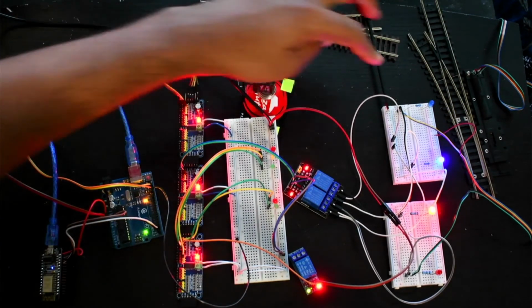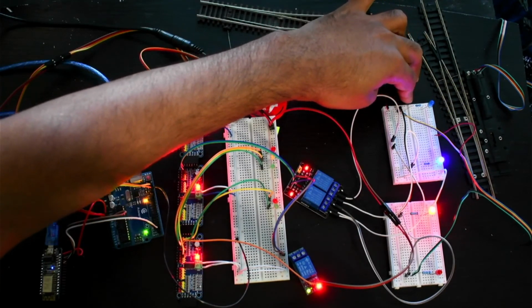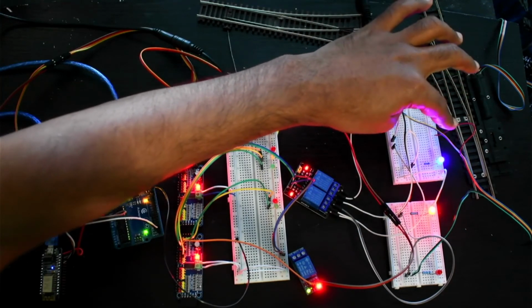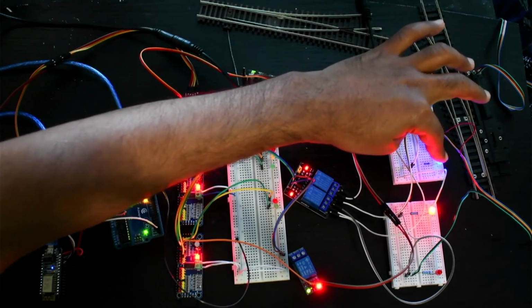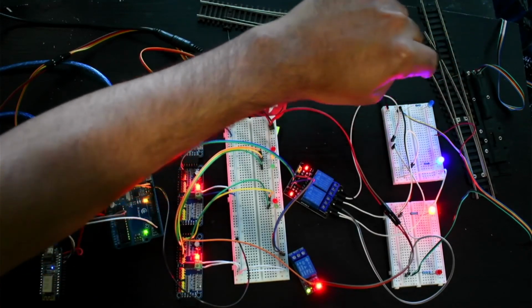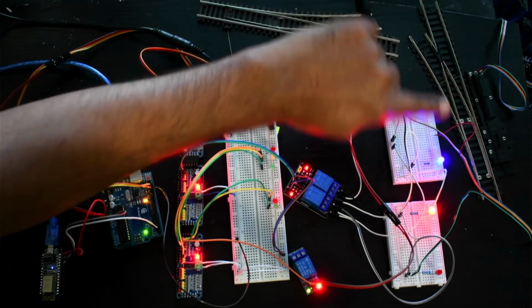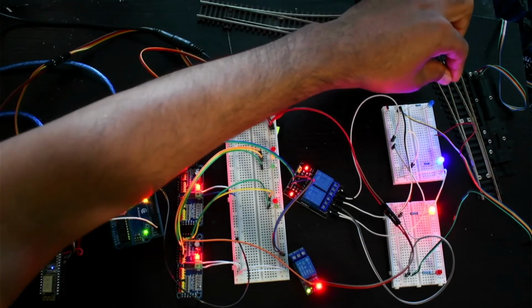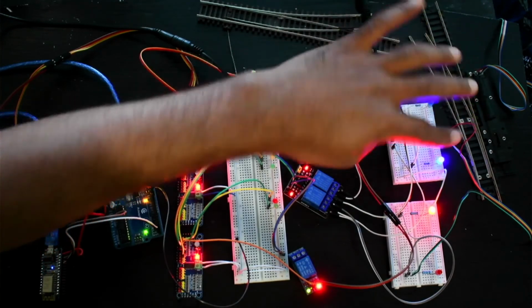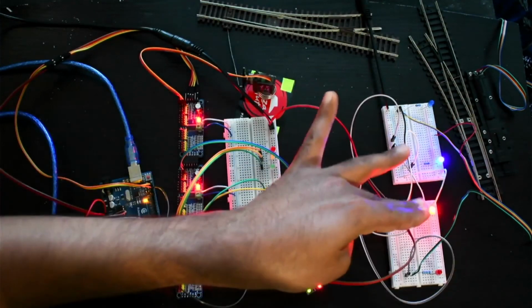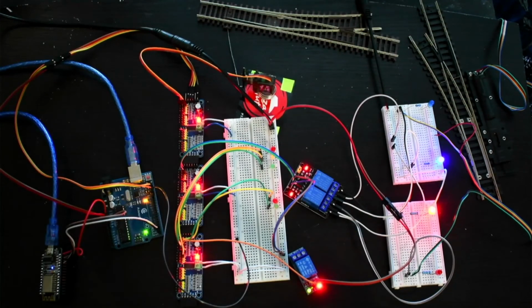So that's the reason I was telling you to keep the connection to that side where light is not on, because if it's continuously powered, if you by mistake configure here, it will burn this turnout immediately, because of this motor here. The concept is that it will give just enough electricity so that it will move and come back. So it will enable this for some milliseconds and come back here, then enable this and go back there. That's the concept of relay switches for Snap Turnout. So this is how the turnout works.